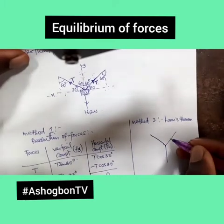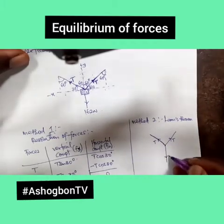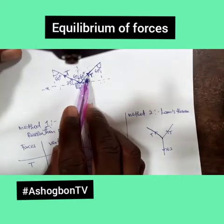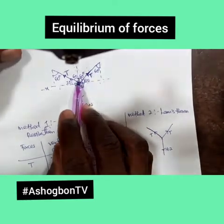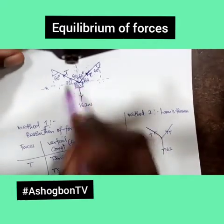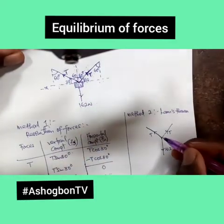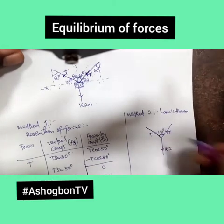Check it out. This is the force acting, this is another force acting, and this is the weight, 162. Now we've already agreed that the sum of this force, we've already done this here, whereby we have 60 alternate angles are equal, isn't it? So if I want to use Lami's theorem, I'm going to add up all these. I will add up these two angles, and if you add them up, what will you get? You will get 120 degrees.